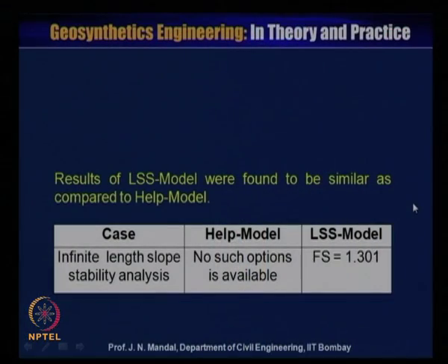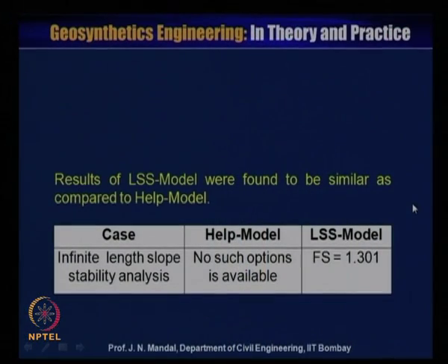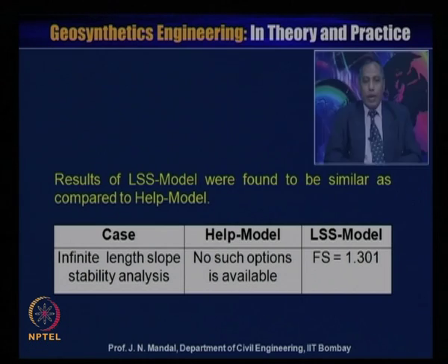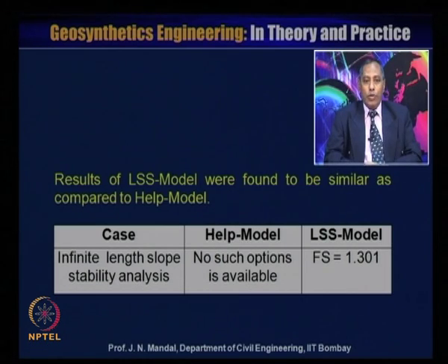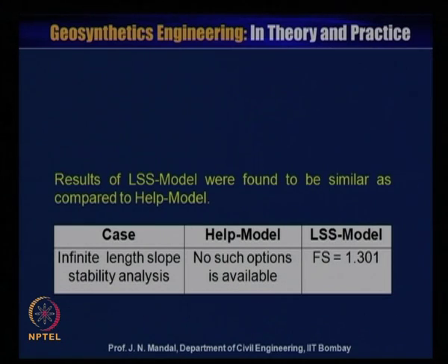Here the result for the LSS model was found to be similar to the HELP model. In the case of infinite length slope stability analysis, no such option is available in the HELP model, whereas the landfill slope stability model gives a factor of safety equal to 1.301. So, it is safe.